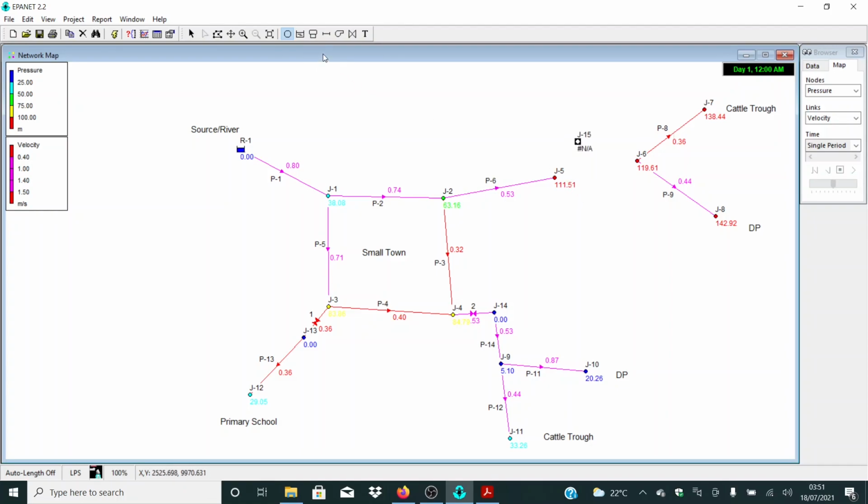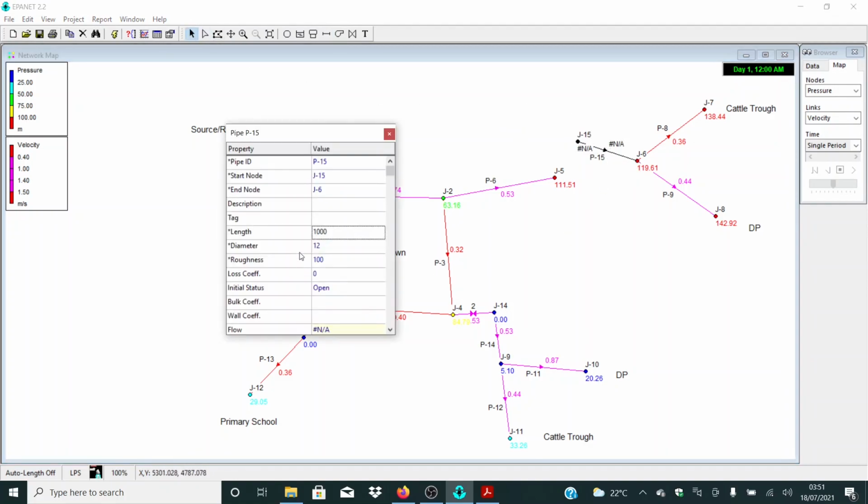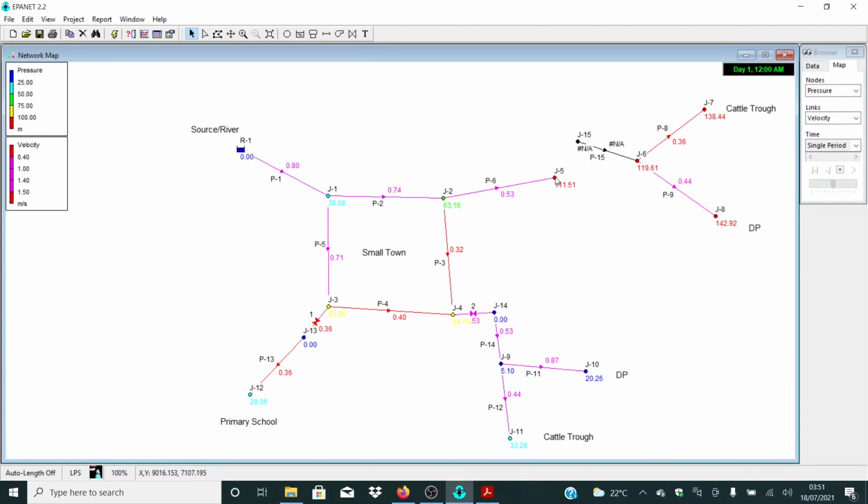Okay. Now, what we need to do is to redraw our link or our pipe. So from here to here, and this link had a value of 260, if I'm not mistaken, 260, and the internal diameter here was 50, and the roughness coefficient here was 0.035, and again we need to introduce a valve here.